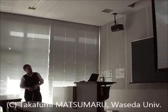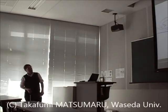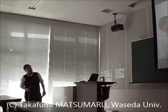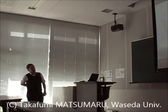This action is creating some vortexes on the surface of the shark. And these vortexes are dissipating energy. Now, if the surface is not flat, but is rough, like we have on shark skin, this roughness is breaking these vortexes, is reducing the occurrence of these vortexes thanks to water trapped in these valleys of the rivulets. The roughness of the shark skin, the presence of these rivulets, makes the shark faster.